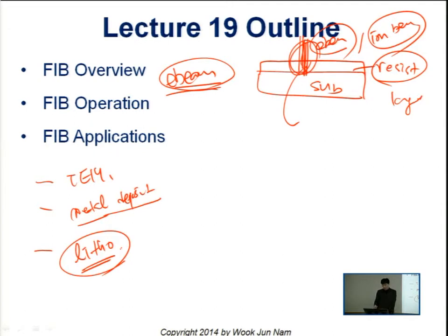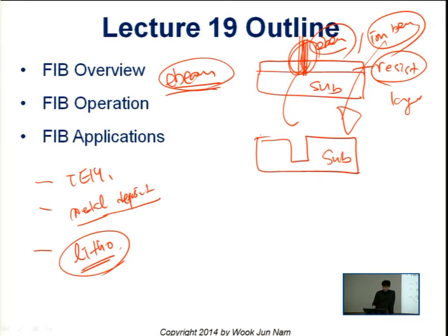One thing we can do only using ion beam, if we want to achieve this kind of final structure on a substrate, is implant ions into this area. So this is the substrate. In this case, we don't have any resist coating. We just simply implant ions, something like this, on the substrate.